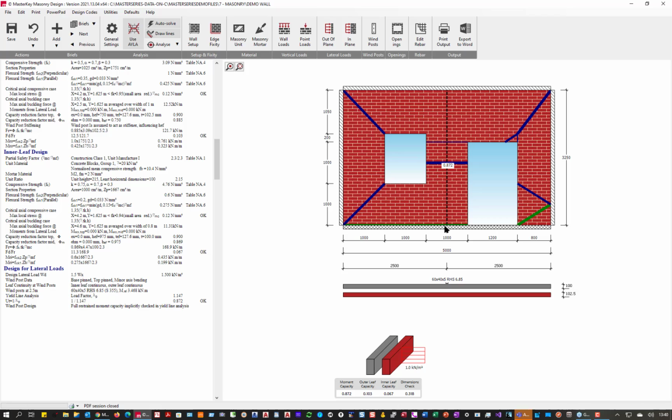Personally, my own opinion is that while that's theoretical and analytically correct, I prefer to see the yield lines going the other direction, where it's actually working as a support rather than just a stiffer part of the member. That's easy enough to get by just increasing your section size. So that's your wind posts and your bed reinforcement and your piers, all done on the frame.